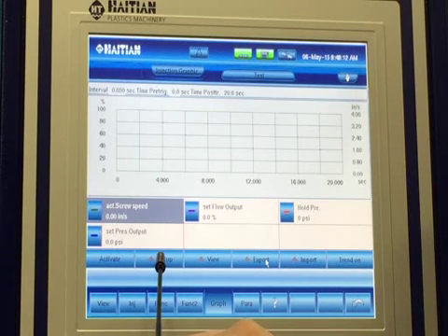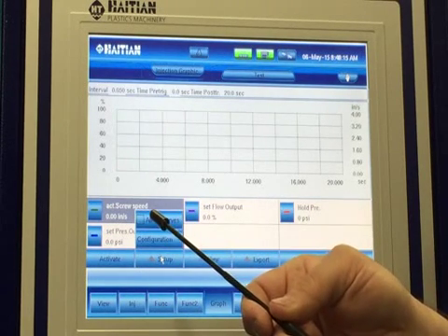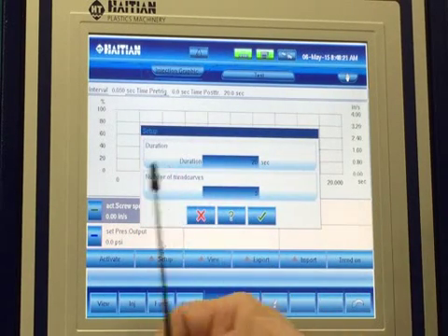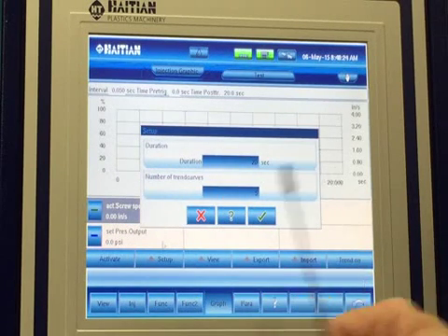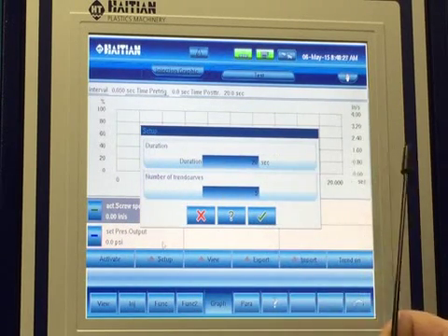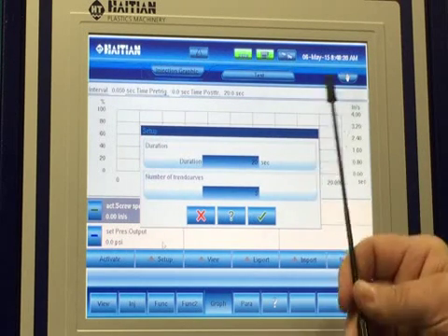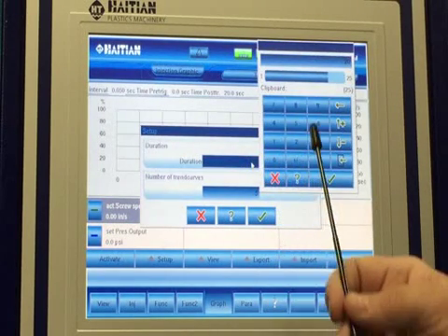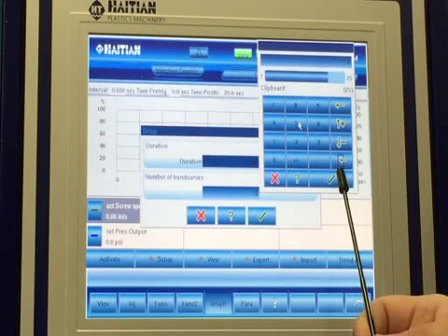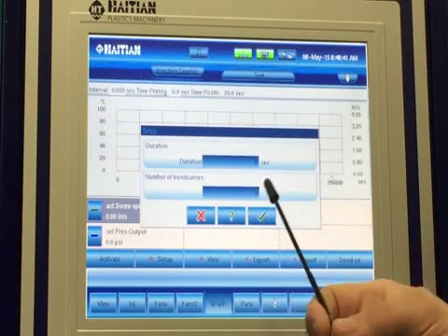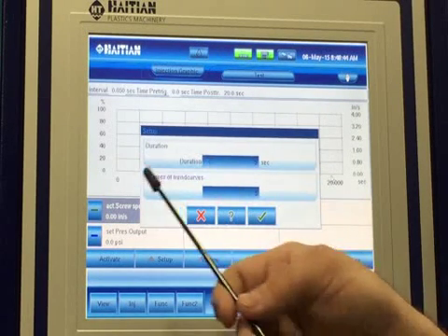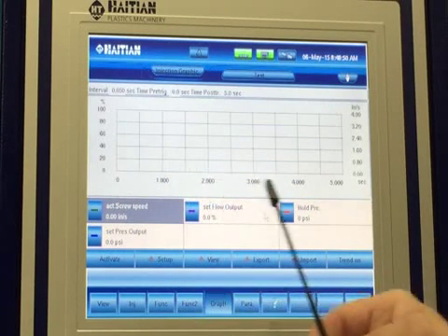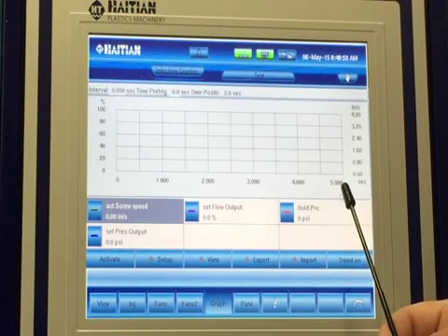The setup key, you can watch all reference curves, or you can configure it. The configuration changes the time across the bottom of the graph from 20 seconds to whatever your injection shot size is. But we know on this example, our injection time is only 4 seconds, so we'll put in a 5. And we're going to monitor 5 trends or 5 curves to see how it's responding. You check your check mark. Now the bottom of the graph has changed from 20 to 5.